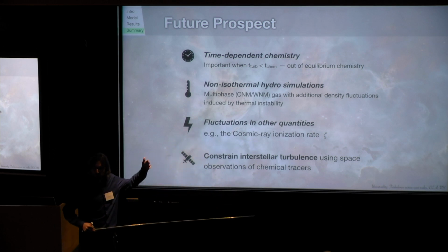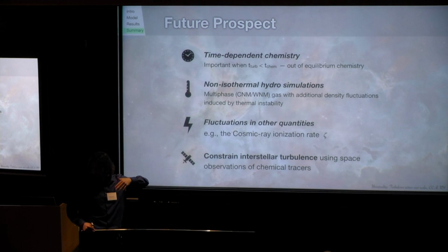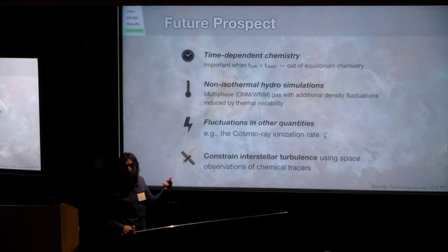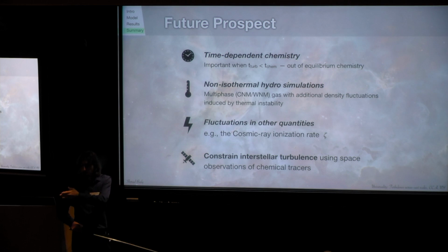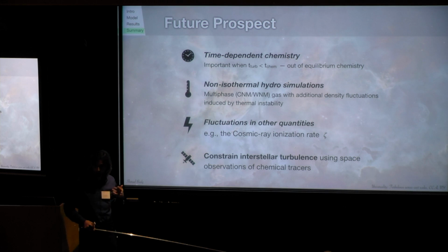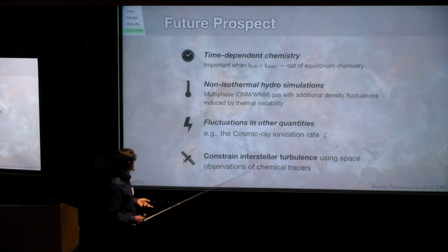Here in this model, we assumed chemical equilibrium. This might be a good assumption in some cases, but not always. Depending on the time scale of the turbulent motions, if it becomes short compared to the chemical reaction time scale, then the chemistry can be out of chemical equilibrium.